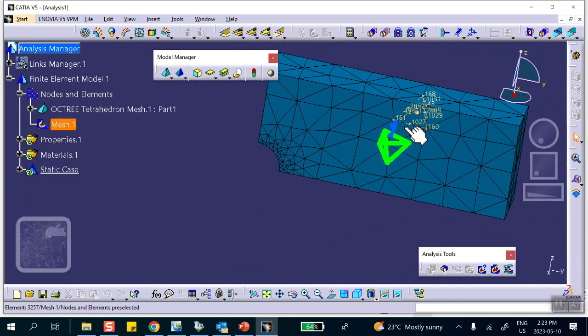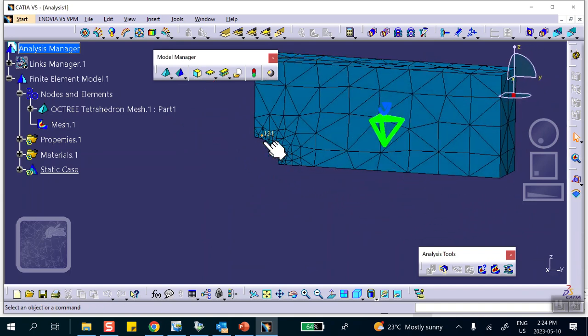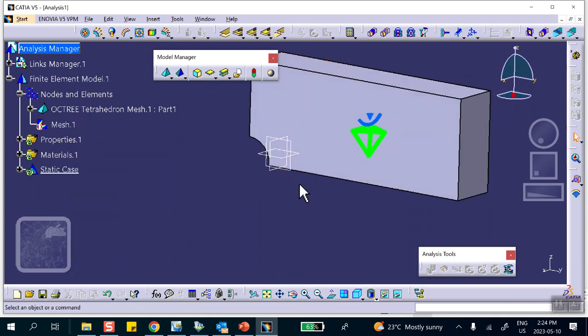Now, you can go and change everything, make everything small, but that's killing a fly with a cannon. There's no reason. The only action is around the hole, in fact, the top and the bottom of the hole, okay? Around the hole, and therefore, there's no reason to go and make a finer mesh in this area. Okay, let's deactivate this. Good.